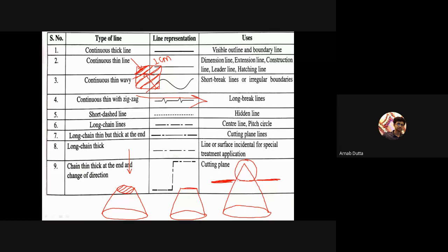In the circle figure, you said that we have to extend the line 2 centimeter. Then actually this will be 20 millimeter. Yes, I should not say 2 centimeter, I should say 20 mm. Normally we are used to centimeters. Every time we are having a scale, we are used to centimeters: draw 10 centimeter line, draw 20 centimeter line. But in drawing, we will always represent each and every dimension in terms of mm. Even if in the question it is written in centimeter, you have to express it in your drawing in terms of mm.